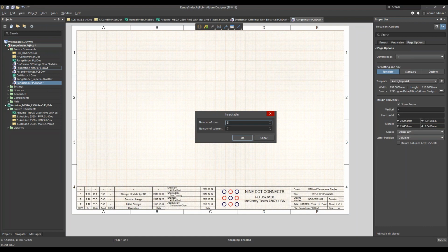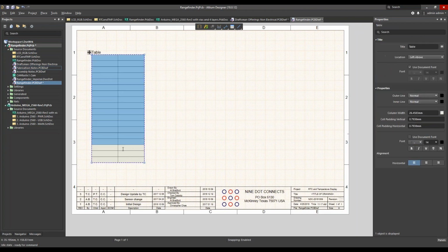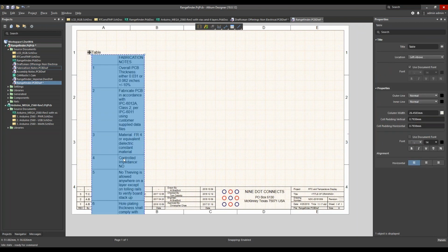It does help to create the right number of rows and columns. You've got to remember this isn't Excel. It's very rudimentary. So you will already have to do some cleanup, but having the right number of rows and columns certainly helps. This one has 18 rows, including the title, and it has 2 columns in it. I'm going to press OK. Okay, so it just brings this in. And if I want, I can put this in here, just do a Control-V to paste it in.